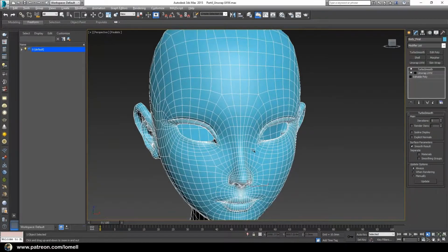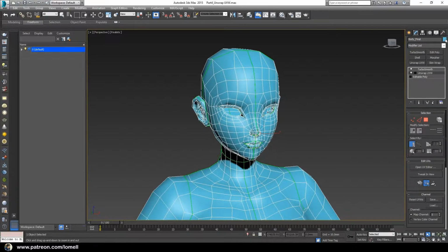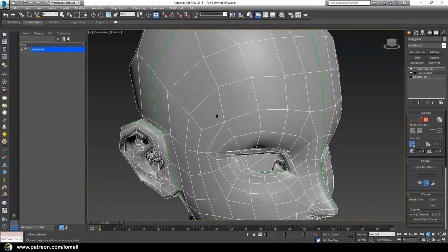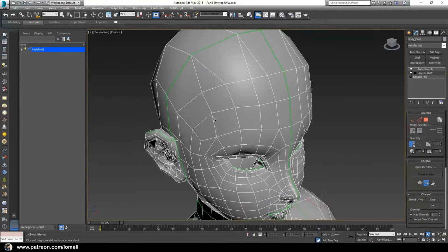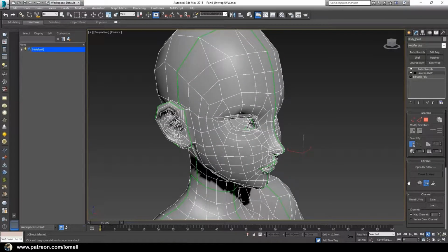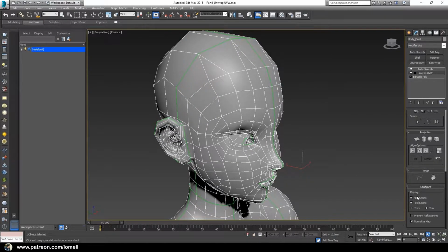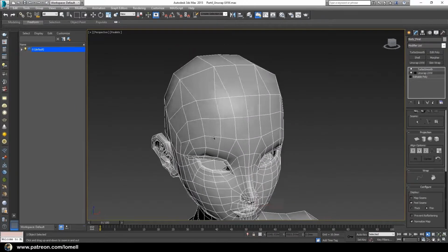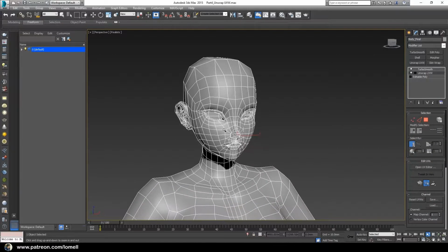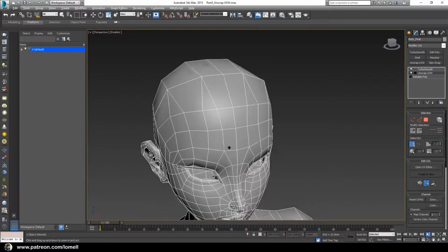Yes. Then click again the unwrap UVW modifier, and let's change the color code to dark gray so that we can see the colors of the seams or the edges that we are seeing right now. Change the seams into thin only, and uncheck the map seams so that we won't see those seams anymore. I'm going to demonstrate how to UV unwrap these objects.